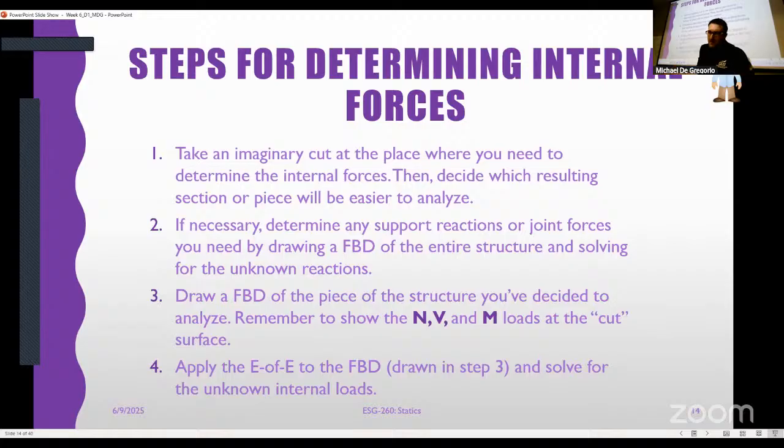If necessary, determine any support reactions. I disagree with this. We talked about this last time. For beam problems, you will see me today, I always start with the reactions, especially if we are going to be drawing shear and bending moment diagrams. You need those reactions. We'll go over a couple of different ways to do shear and bending moment diagrams.